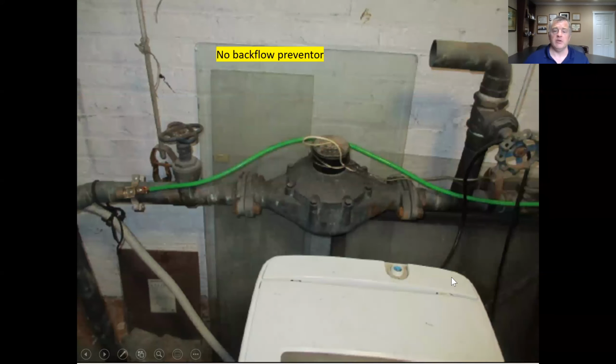No backflow preventer in water systems. That's going to have to be installed as a safety device so you don't get a reverse siphon and send contaminated water back into the potable system.